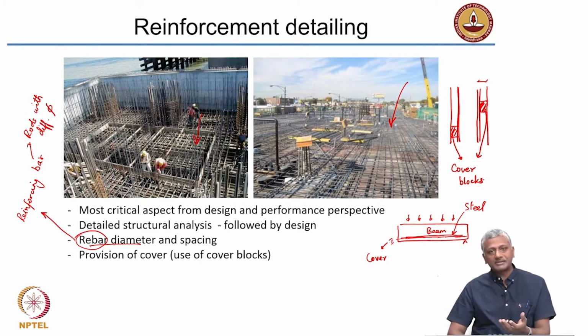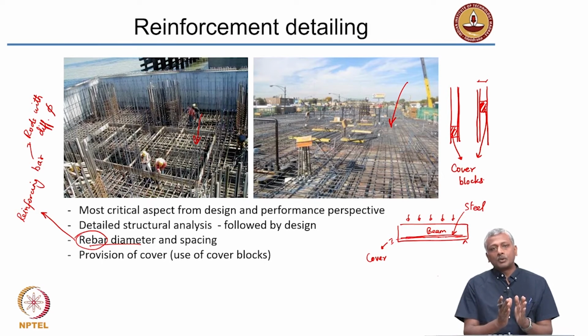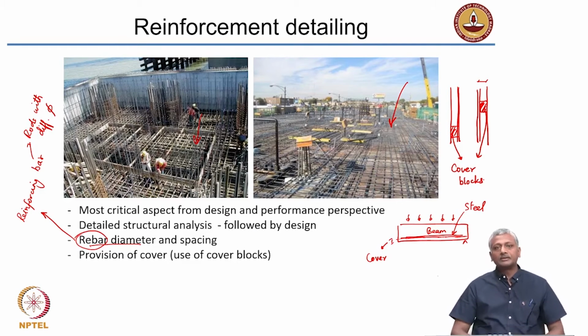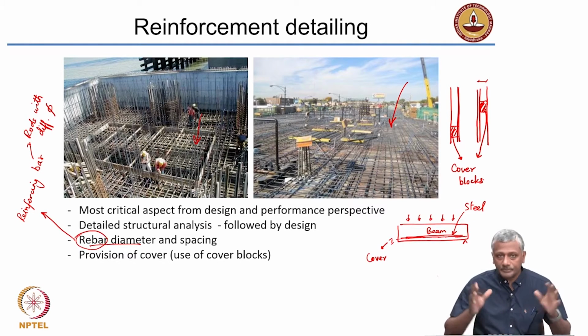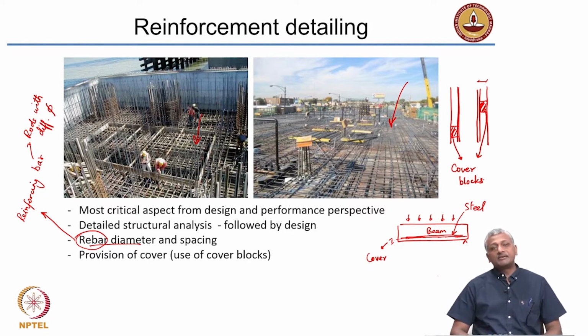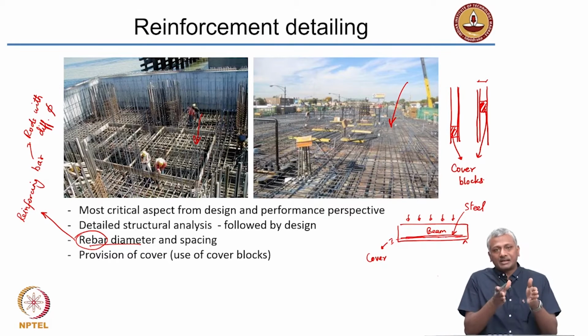Again, if you go through design practices, you will understand that the thickness that you want to provide as a cover is determined by the kind of environment that the concrete is in. For example, if your concrete is in a coastal or marine environment where it's going to be subjected to very harsh aggressive conditions, because there are a lot of chlorides that can cause corrosion of your reinforcing steel, then to ensure that the steel does not corrode in the lifetime of your structure, you need to provide a thick enough band of concrete around the steel. That's called the cover, and in most marine conditions, for structures like columns standing in seawater, it could be as much as 75 millimeters. So, how do we exactly provide 75 millimeters?